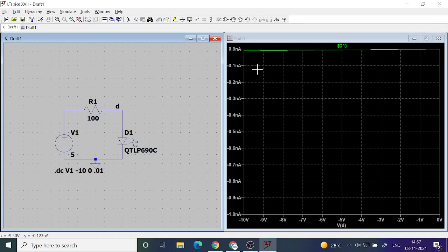That is not breakdown, that is the device turning on. It is wrong to say breakdown. Breakdown is an entirely different mechanism, which happens in the case of Zener diode that we saw in the reverse bias condition. That is breaking down. But when you forward bias a diode, any diode, it will turn on at some point of time, which we call the cut-in voltage.